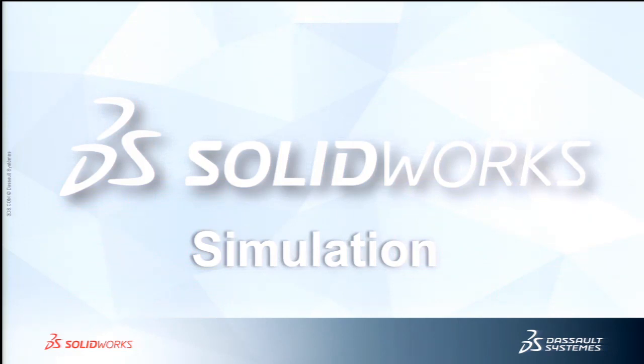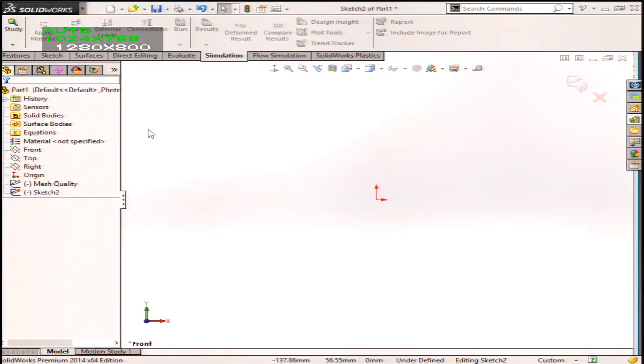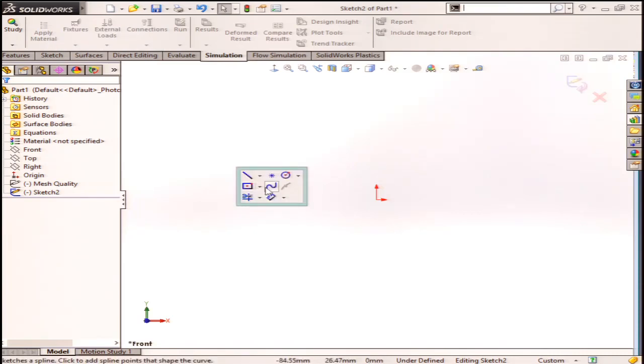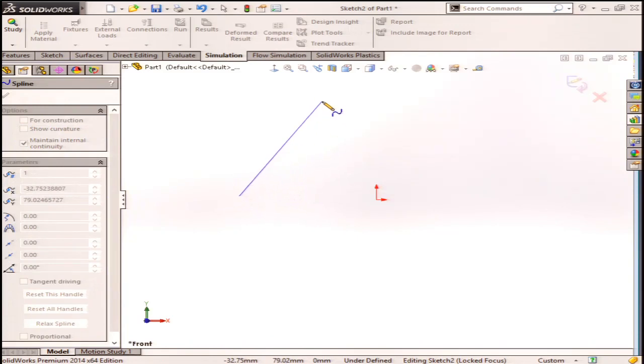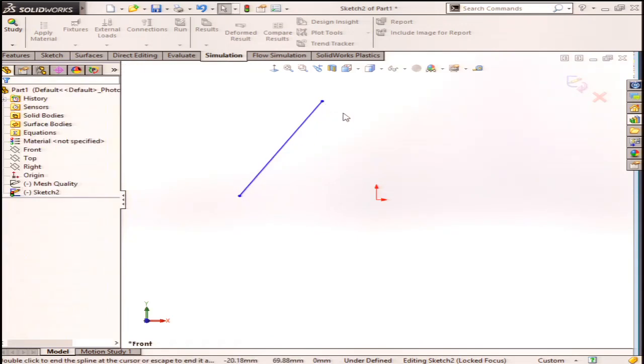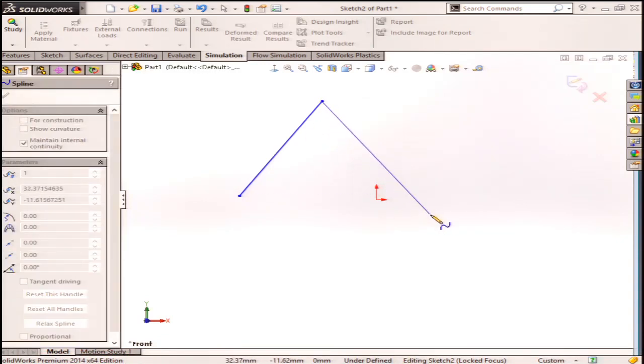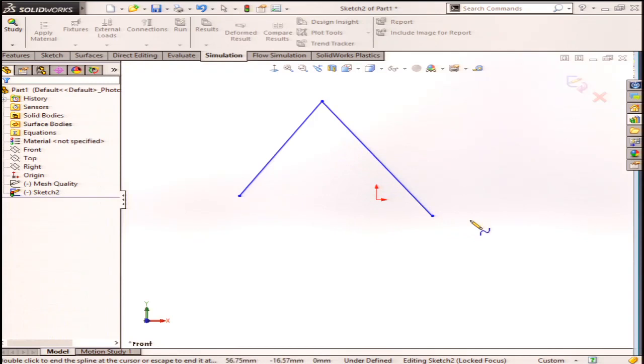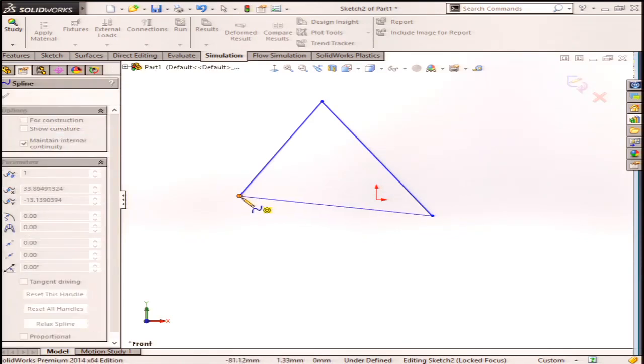So let me switch over here. So what's the difference between these elements? What does this really look like? So if I come in here and I draw, so real quick, I just drew one line, and if I want to get back into that exact same command, you guys know this shortcut, if you just hit the enter key, it goes back to the last command you just did. Who knew that? Who did not know that? Who just learned that? Right, so I'm going to do line, and I'm just going to draw it. I want to go back to the line command, draw it again, hit enter, and then I'm back in.